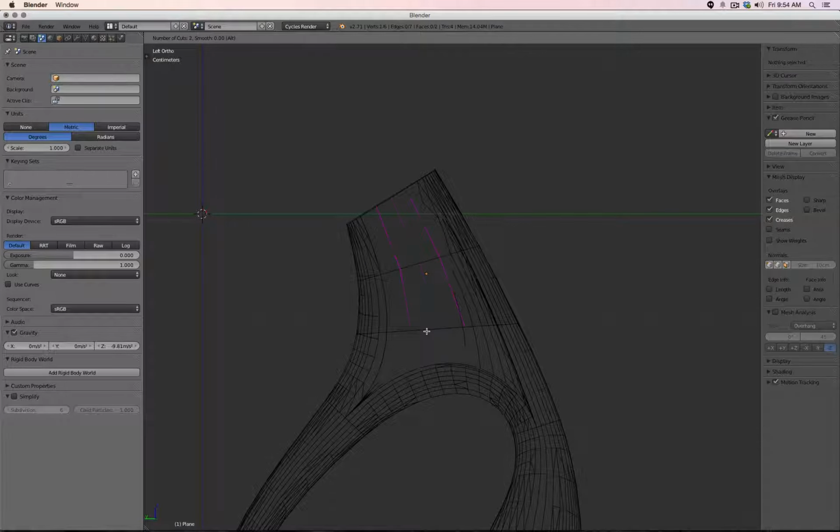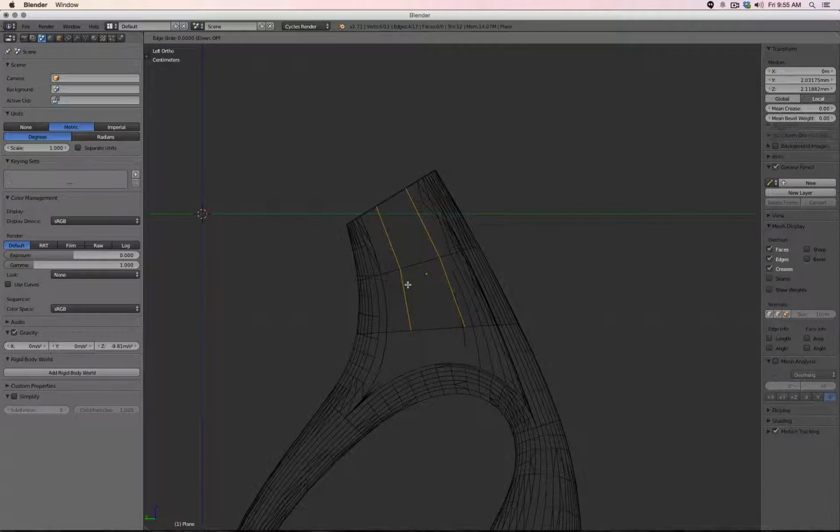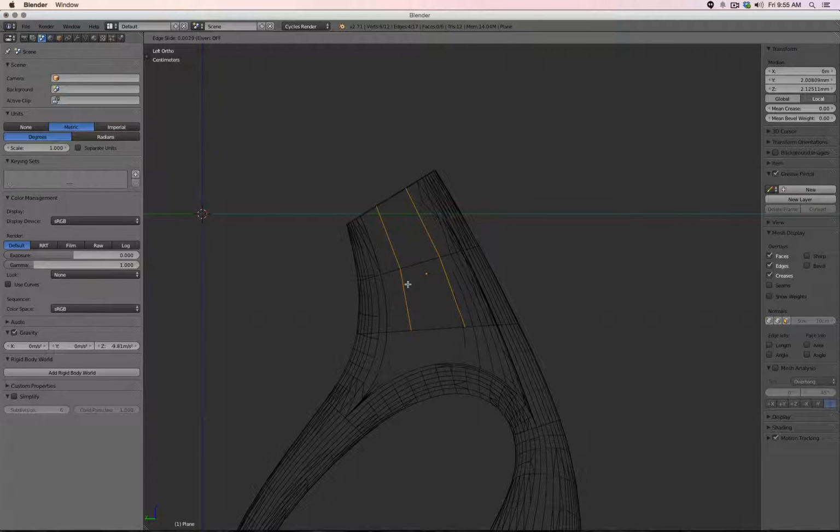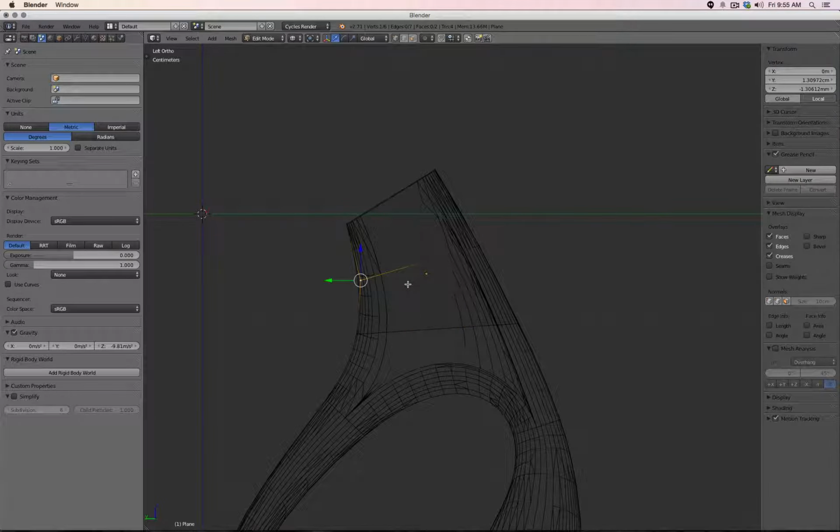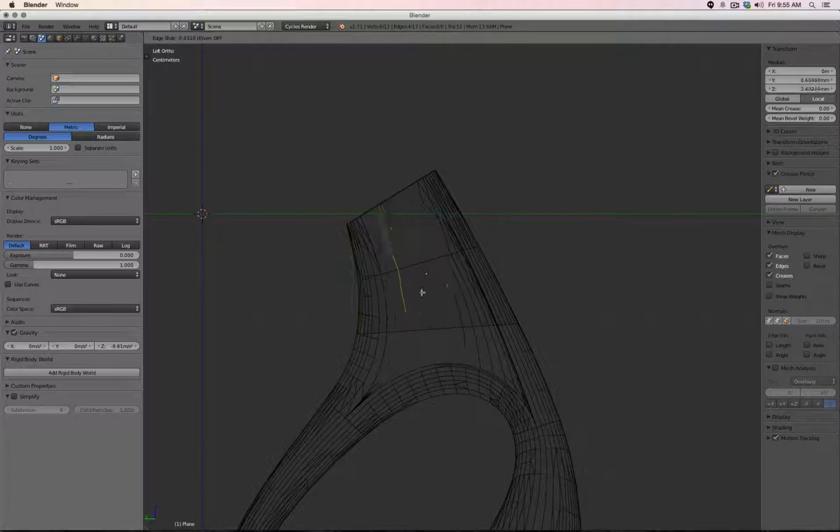So with Control R, you see when I go into an edge and I'm in edit mode, one movement on your mouse wheel, you can change the subdivision level or the cut level. So I make 2 cuts. Press 0 and enter so they don't slide. Just let me show you what sliding means. You see I can slide them. That's what I want. So 0.